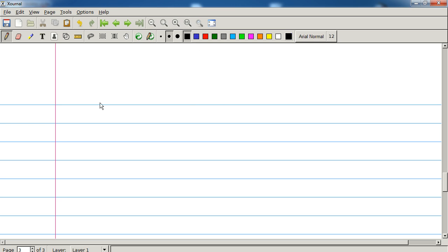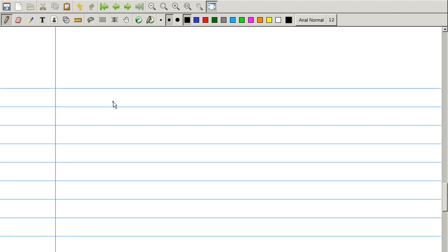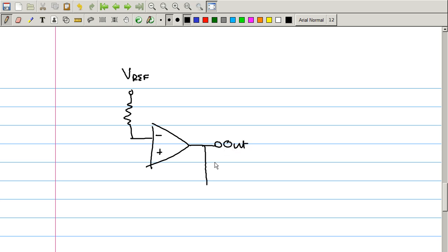So for that formula, if you use the schematic I just showed you, you have Vref. You've got a resistor, and that goes into the op-amp, the inverting input. This is your output, V out, that's what generated that hysteresis loop. That connects to another resistor, which connects here, which then connects to one more resistor, which goes to ground.